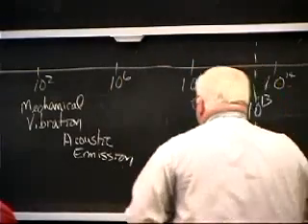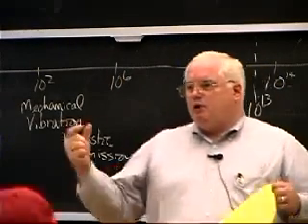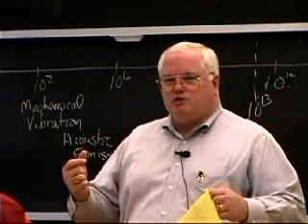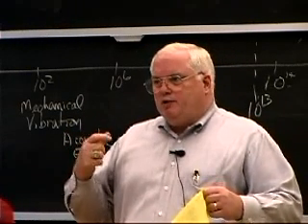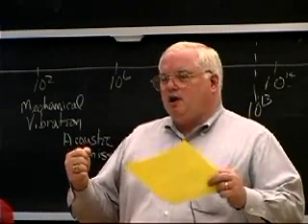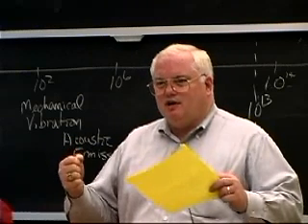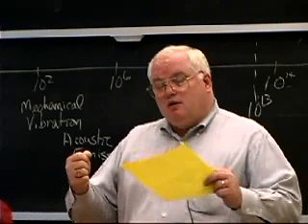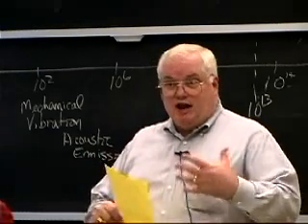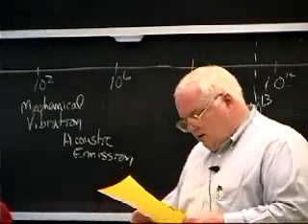So acoustic emission is I take something, I strain it, and then I put a transducer on it to listen to see if it makes any noise at fairly high frequencies, above my ear usually, I mean 100 kilohertz or something. If the thing's under stress, a lot of times it will sort of cry out to you. You can't hear it. Maybe the dog can hear it, I don't know, at higher frequencies. But people use acoustic emission. You just put a stress on it and then you see if the material has a flaw and that crack is starting to slowly grow, it will essentially put little stress waves through as the crack grows.